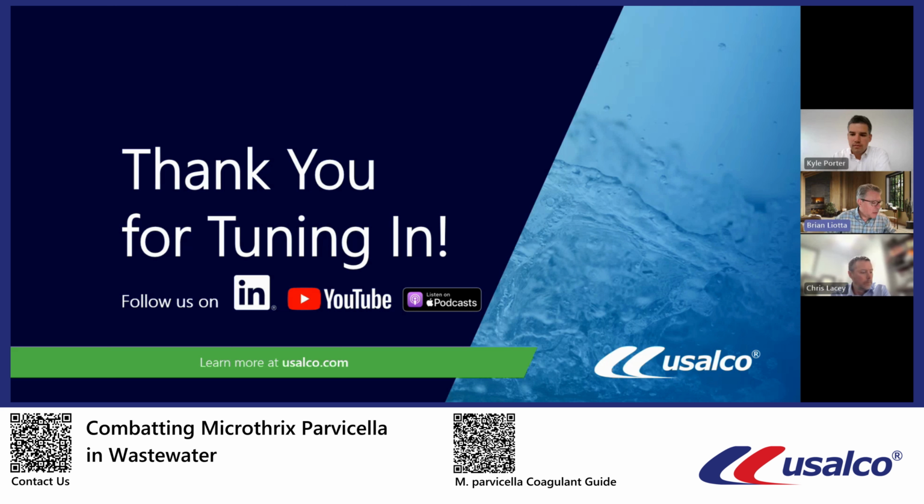The last question that I see so far is, how long will it take to see results? Often you'll see it pretty quickly, in five to ten days, but more often than not, the easier way to think of it is that it usually takes a sludge age. When you're hitting it with that initial dose, it can sometimes be much faster because you're hitting it with a really strong, quick overshoot. But worst case scenario, you should see it within a sludge age.